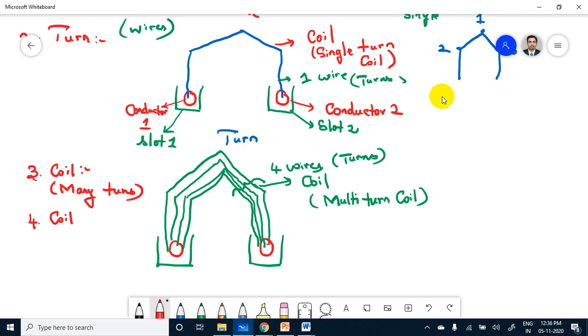And the fourth one, 1 by n, x of minus k, is the coil side. Coil side means the part of the coil in each slot. Here you see the edges, in one slot there are 4 wires connecting, right?